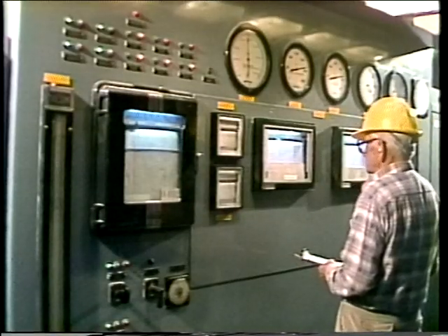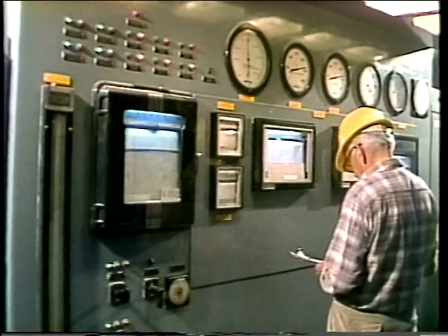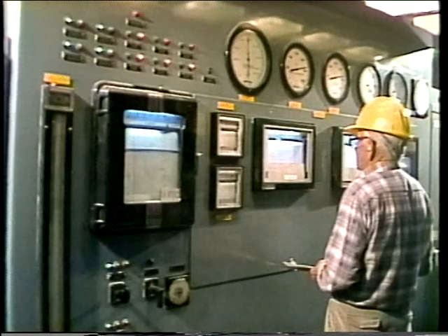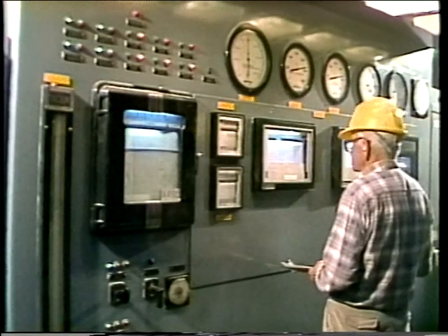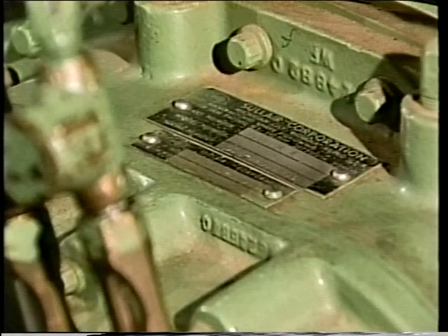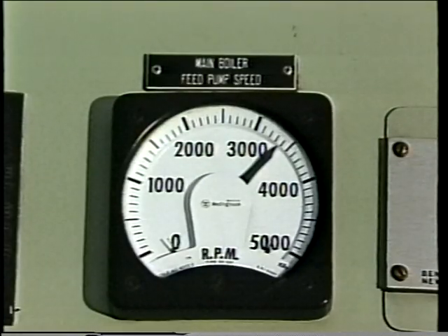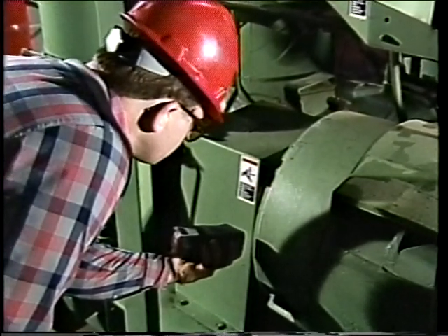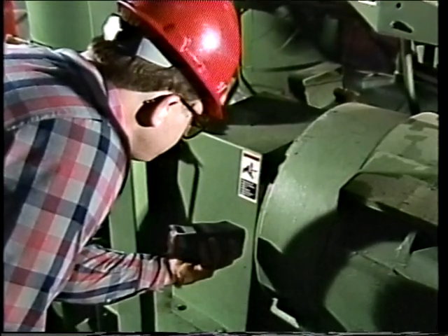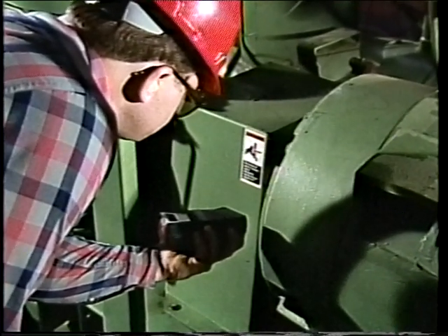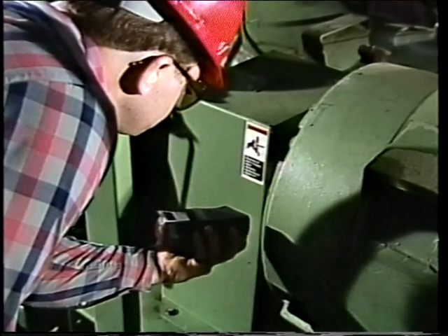The operating speed of the machinery is normally checked, even though it's relatively constant on most machinery. A machine's speed can be determined in a number of ways. For example, most machines have a label plate that lists the speed. Some machines have a permanently mounted tachometer, others do not. In this case, a portable tachometer could be used. When using a portable tachometer, be sure to follow the manufacturer's recommendations for that particular unit.